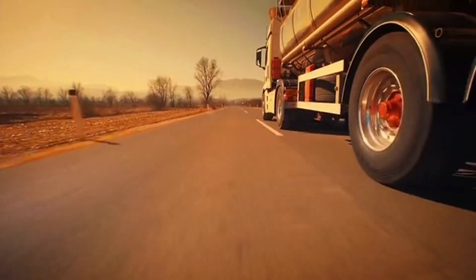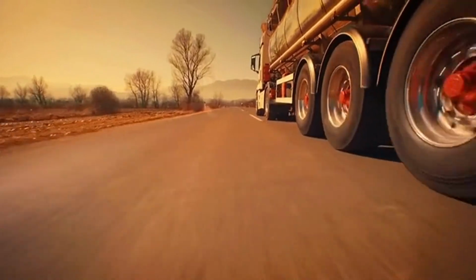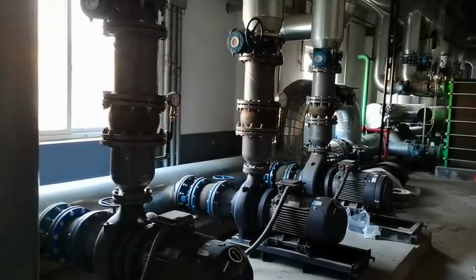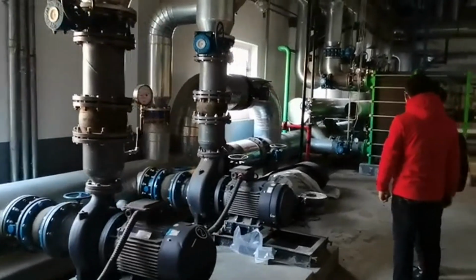Large shovels scoop oil sand into haul trucks that transport it to crushers where large clumps are broken down. The oil sand is then mixed with hot water and pumped by pipeline to a plant called an upgrader, where the bitumen, oil, is separated from the other components such as sand, clay, and water.